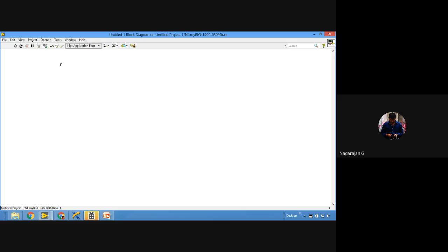Now, whenever you're trying to develop any program under RT, your FPGA will not do anything. We call this scan mode. It will directly take all the data from the FPGA and route it to the embedded processor, the controller. So the FPGA will not do any processing. If you develop any code under FPGA, then only the code will get processed by the FPGA hardware.